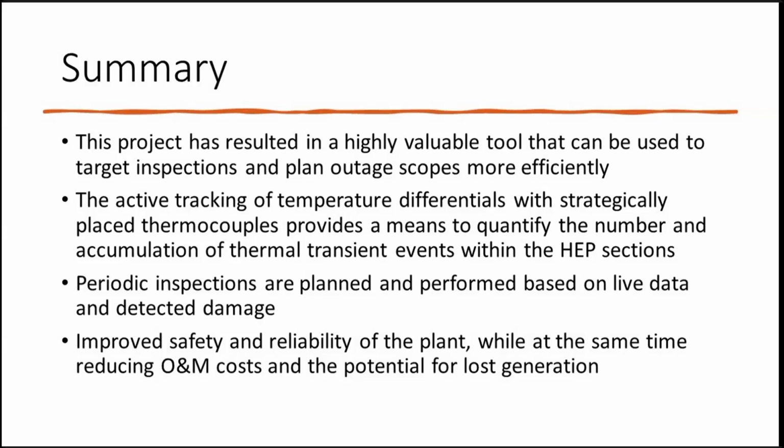It's not very complicated. There are a few key steps that have to be done, but it's not expensive and doesn't take a horrendous amount of skill. Yeah, and I also wanted to mention that you don't have to do the post weld heat treatment, even if you attach to a grade 91 tube. The code allows you, as long as you meet certain requirements and have certain energy levels or less, you don't have to do the post weld heat treatment or preheat. So that really helps things when you're attaching to grade 91 components.